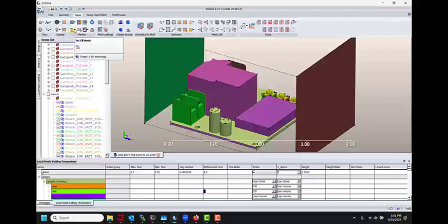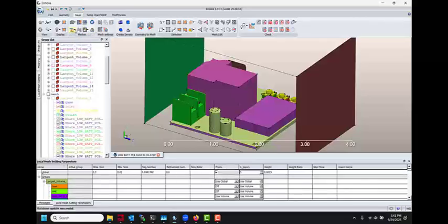So, setting up the volume mesh, that's this little triangle here. I'm going to go out to a polyhedral mesh. Polyhedral mesh is quite useful for these types of flows and the solvers for analyzing these flows, especially if you're going to OpenFOAM. But first of all, let's just do the inflation of the prism layers that we just set up.